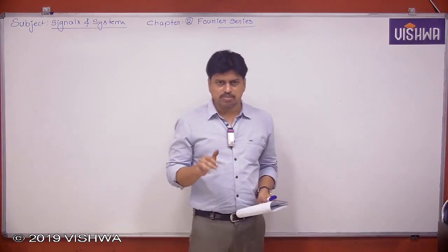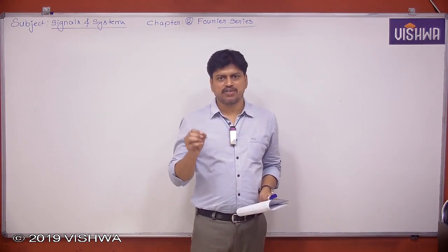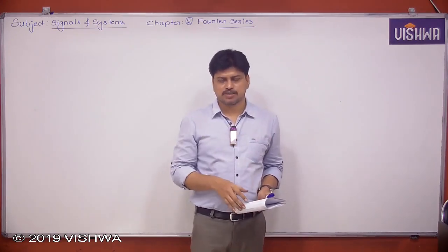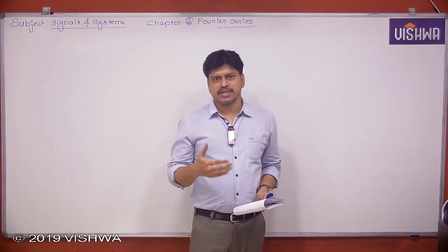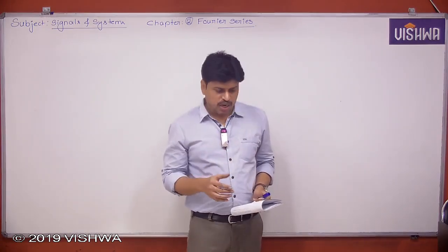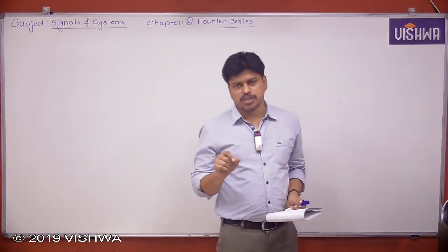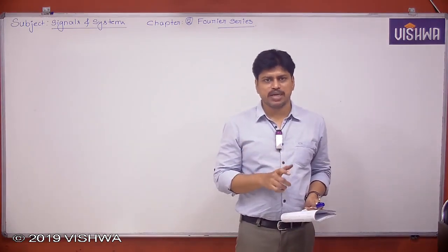If there is no jump, only amplitude, then for a positive amplitude everything is plus minus like that. If it is a negative amplitude, then it is minus plus minus plus. And I told you how to find the Fourier series coefficient. The formula is 2 into maximum value minus minimum value by n pi.